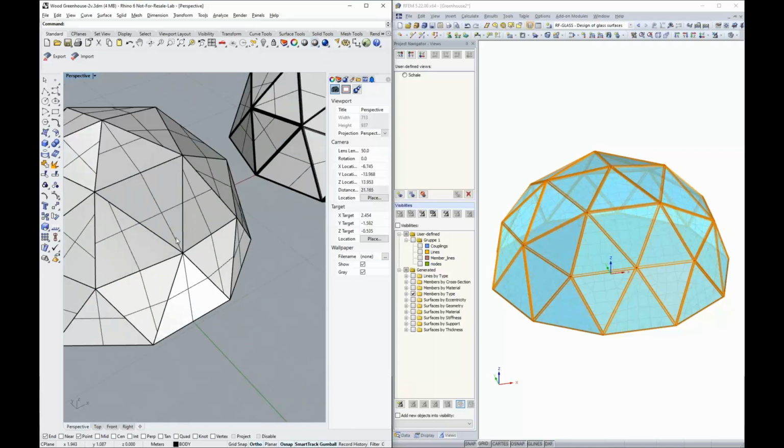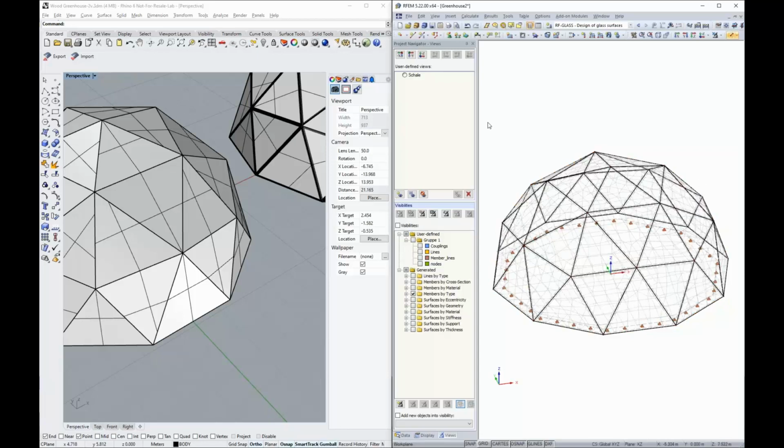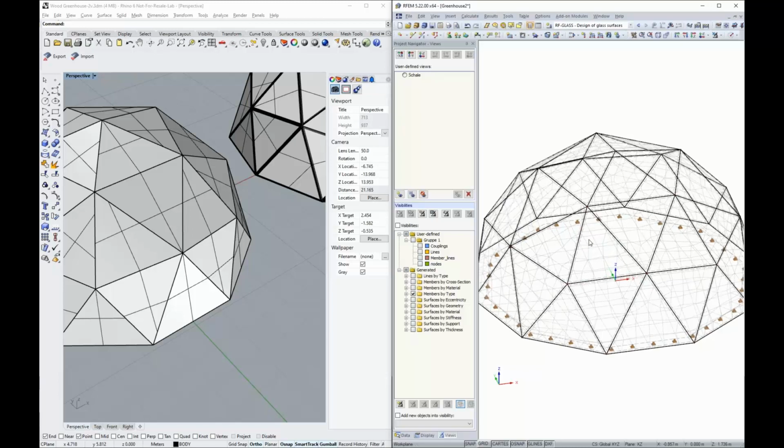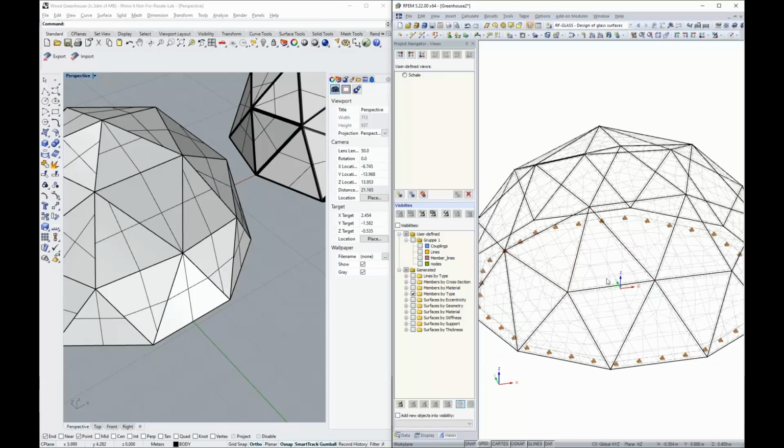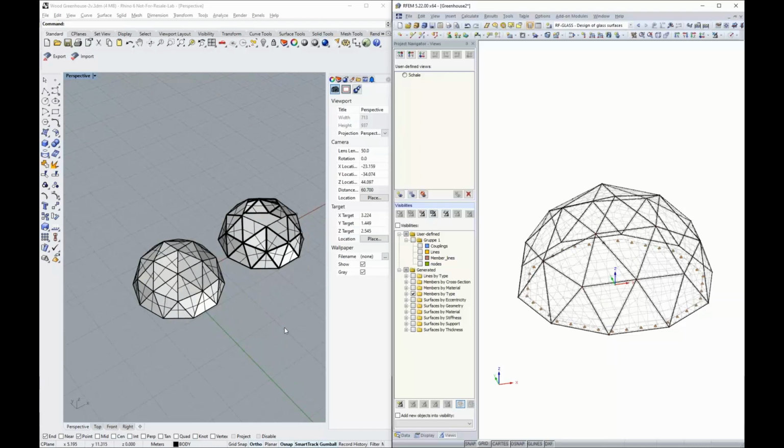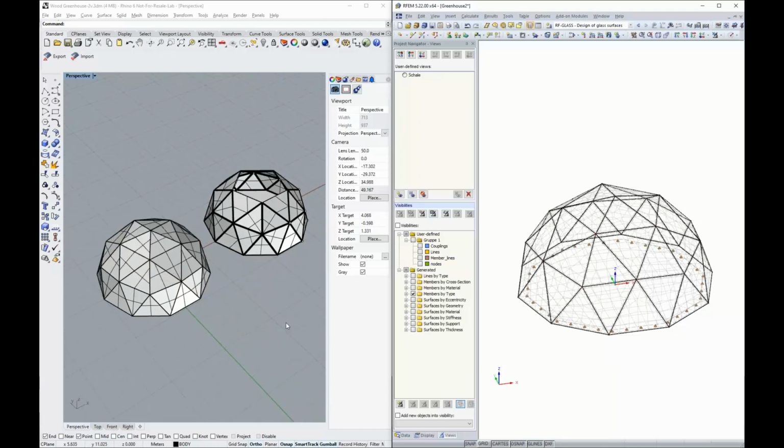I can see the surfaces and also more or less the lines that surround the surfaces, but no members or anything like this, simply because we import the wireframe structure. And the member is not a real object in this case, it's just a line with additional information. So we import lines and surfaces. This is basically the data exchange between Rhino and RFEM. It's a quick tool to get your Rhino data in RFEM or the other way around.